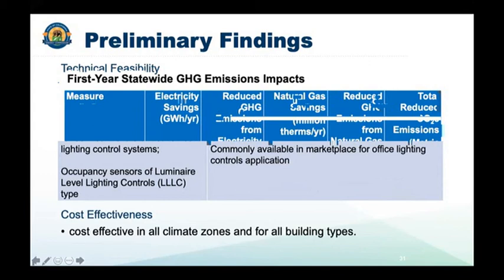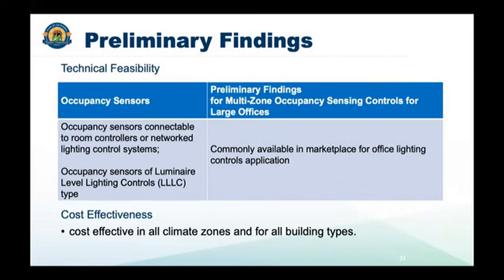There is a relatively new approach of placing the occupant sensors at the luminaires, also known as luminaire level lighting control, LLLC. The benefit of this approach is an increase of granularity of the control area, if the control decision of the luminaires depends on the luminaire sensor detection.